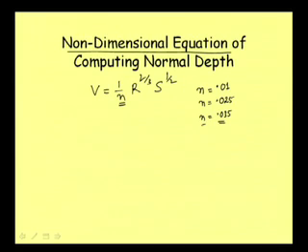When we write about velocity, we write this much meter per second, depth this much meter, but here we are just writing some value. So we will have to be very careful in using this formula. In fact, this n is not a non-dimensional term, it has some dimension, though we are not writing the unit. And that is why when we are using this, we are using it for a particular unit of V.